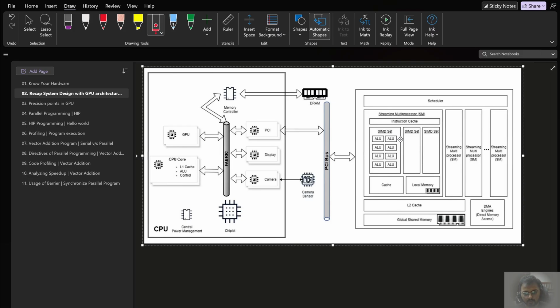One more parameter that we have seen is that there is an instruction set executor in each compute unit. In the specs of the MI300X, we noticed that it has 4 SIMDs per compute unit. So here what you see, there are 4 SIMDs, and every SIMD would be able to process the work group as a wavefront. So we have also noticed the wavefront size.